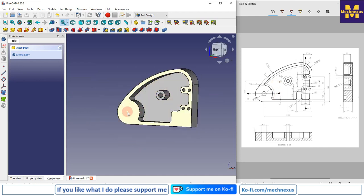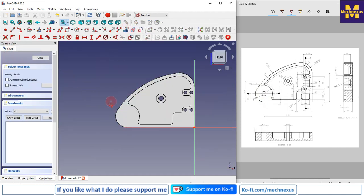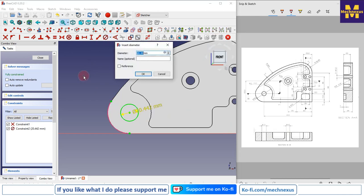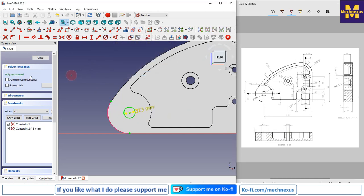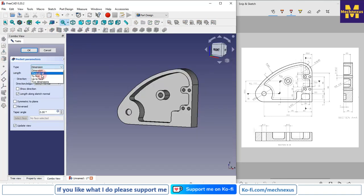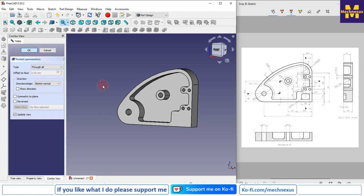Now here is one hole, so I will select the face and create a sketch, and I will project the outer arc, and now I will draw a circle, and this hole diameter is 13, so I will select this and give diameter 13, and I will close it, and I will say extrude, and I will say through all. I will say OK.